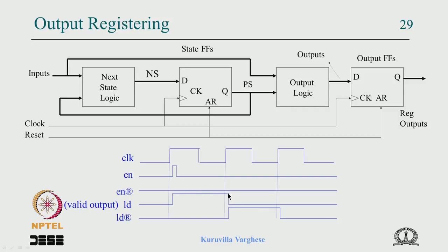So in the critical case it remains there for one clock period, but when this clock edge comes it is high, so the registered version of that output comes at the output with a 1 clock cycle delay. That means all the glitches go off, but all the outputs lag by 1 clock cycle with respect to the state change. But it's less of a problem.